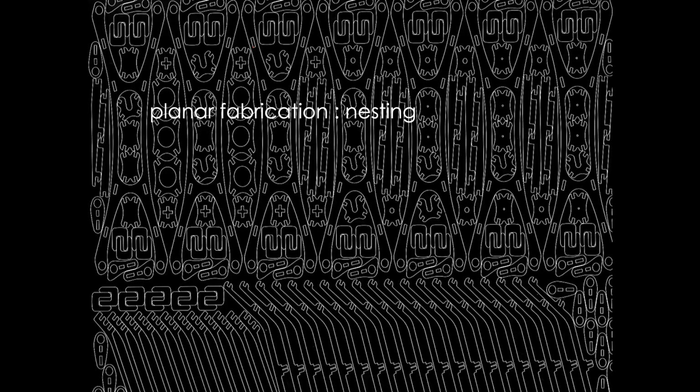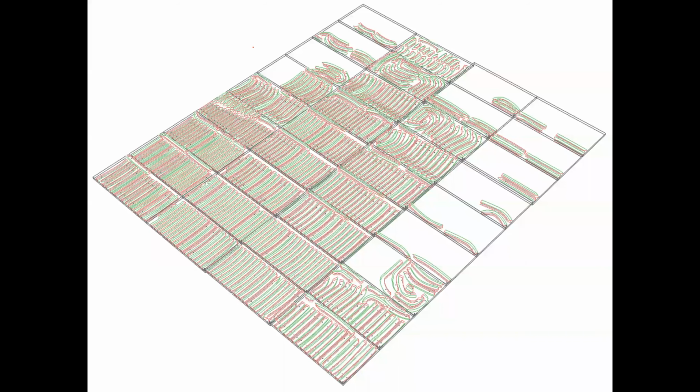Second to last thing, this idea of nesting. This idea of yield, of trying to minimize waste. These are all components to be laser cut, and you can see that they're nested together to minimize the amount of waste. All these offcuts, if they're odd shaped and really small, are just going to be thrown in the trash. So make sure you nest things out to get the most yield out of your materials.